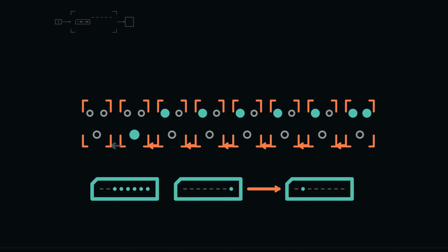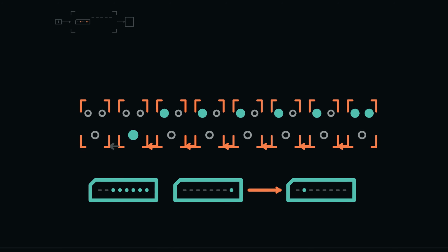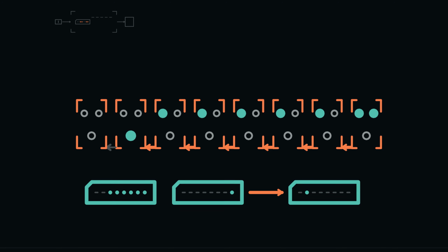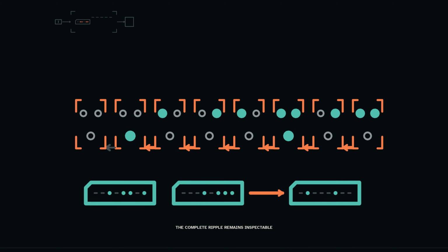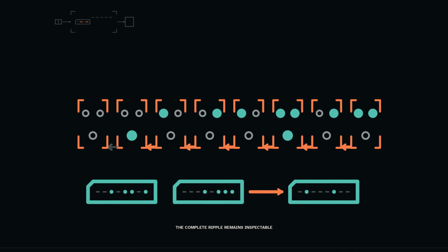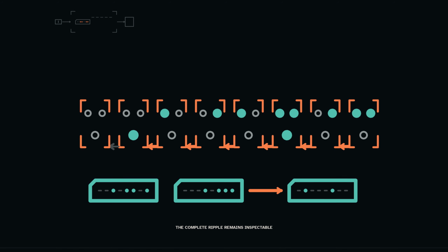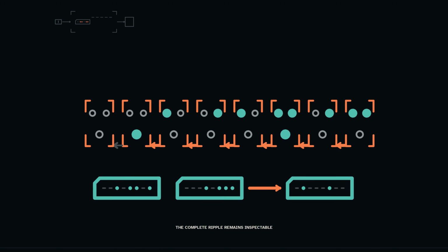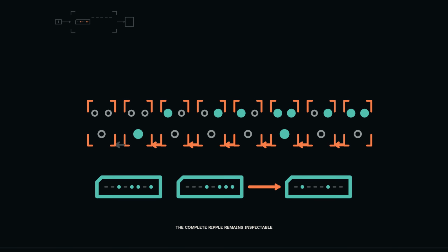The longest visible change is not evidence that a numerical object traveled. It is the consequence of one local dependency repeated until a position can absorb the carry. If carry leaves bit 7, the 8 sum outputs still contain only the low 8 bits. The 9th fact is available separately as carry out. That is the hardware relation behind the fixed width behavior we interpreted earlier.